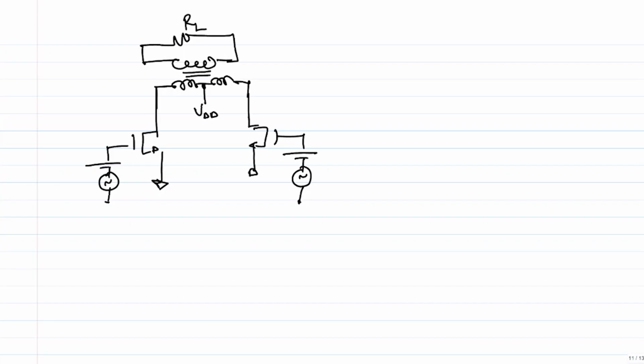So what will be the efficiency of this arrangement, right? In order to find out the efficiency, all we need to look at is, so by the way, what are we basically saying? We're basically saying that each of these are drawing some current ID, right? So I can find out the power dissipation from the DC current that I am drawing, and if I know the sinusoidal current, then I know the power delivered. The ratio is essentially the efficiency, right?